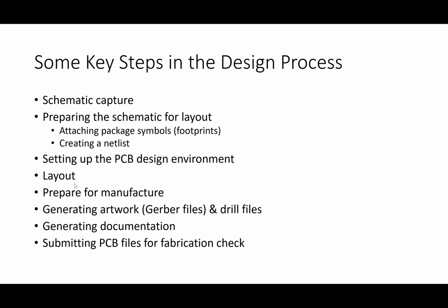Then basically you're going to generate the files that are used to actually create this. Now in the initial video, Chandan doesn't really talk about these elements. We'll talk about some of those later. But basically what we're talking about is what we call our Gerber files, or our artwork. These are the files, along with our drill files, that tell the manufacturer how to manufacture the board.